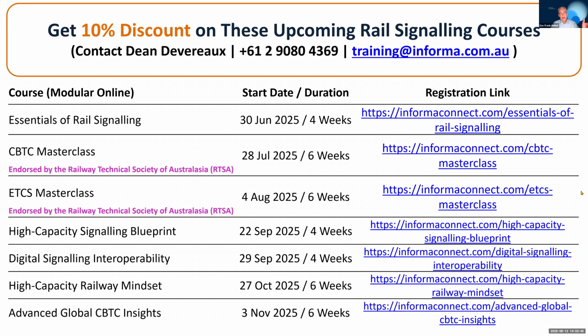Normally you have a very clear differentiation and also separation between railways that operate on CBTC and railways that operate on ETCS. A good example in Australia is Sydney, where you have Sydney Metro using CBTC, and the Sydney Trains network using ETCS, and both networks are completely segregated without any physical connection of tracks. And this is how it should be. If you do that, then you don't need to consider interoperability between those systems, or any interaction transitions. The problem just goes away.